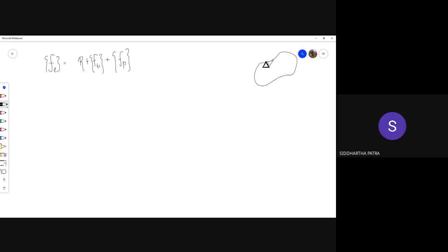At some location you are applying a concentrated force of P, and that should correspond to a given node. Once the element stiffness matrix has been found, you assemble the element stiffness matrices into the global matrix. When you are solving the global problem, that's where you apply this P. Otherwise, you do not know whether to put this P for this element or the other, because it only appears once in the global system of matrices.